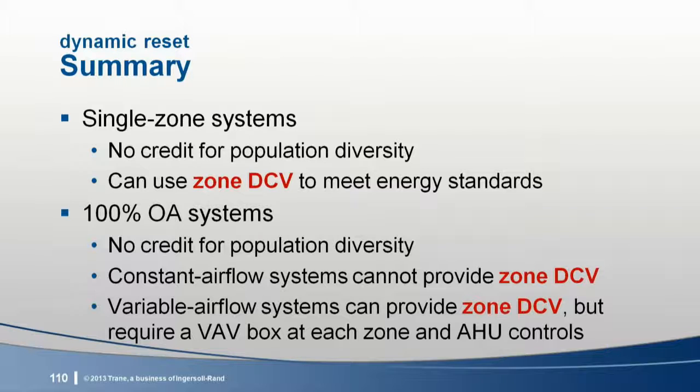The outdoor air supply must be VAV, and as I just mentioned, every zone in the system must include a pressure compensating VAV box to maintain proper outdoor airflow. We know how to do this too, and it saves energy, but it increases first cost.